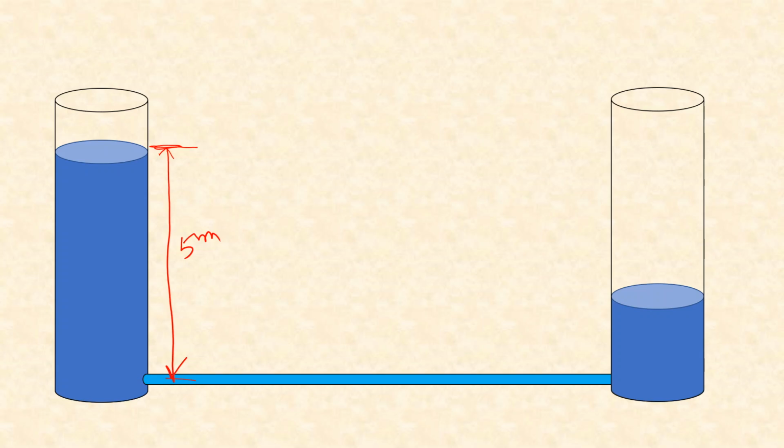Now in the second tank, let's say for example the water level is again 2 meter. Now this 2 meter is again measured in this tank from this water surface up to the center of the exit point of the pipe or entry into this second tank. So that's how these heads are measured.